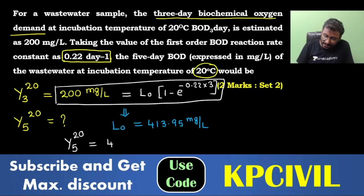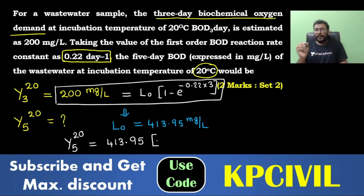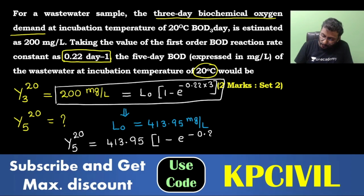The universal equation is L0 into 1 minus e power minus kt. L0 is 413.95, k is 0.22, time is 5 days. The universal equation gives BOD at any time and at any temperature.